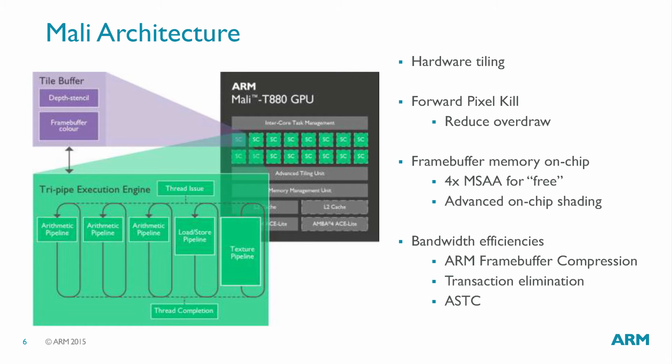Now, there is also on the chip a dedicated hardware tiling unit. This is the thing that actually does the geometry binning. It's not something you can control really anyway, so it makes sense to just lock it down in hardware and flush everything through. You should sort of think about it as semi-being magic. There's also this funny kind of thing called forward pixel kill. Now, this is sort of like hierarchical Z, but on drugs.